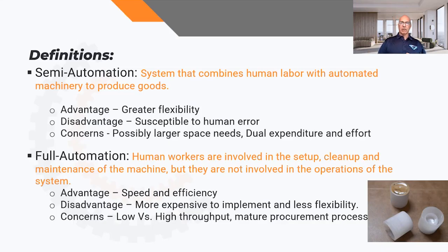The disadvantage, however, is that it's susceptible to human error, and there are some possible concerns there, like possibly larger space needs and maybe dual expenditure, because eventually you're going to go to full automation. On the full automation side, human workers are involved in the setup, cleanup, and maintenance of the machine, but they're not involved in the operation of the system as the parts are being built.